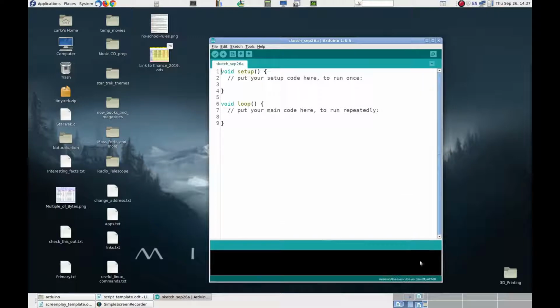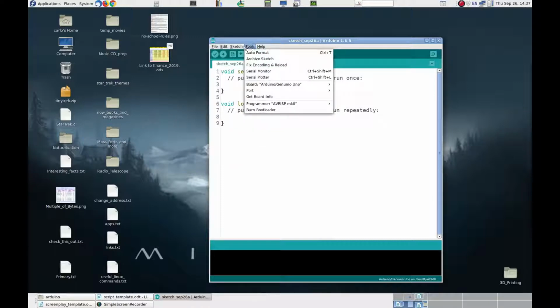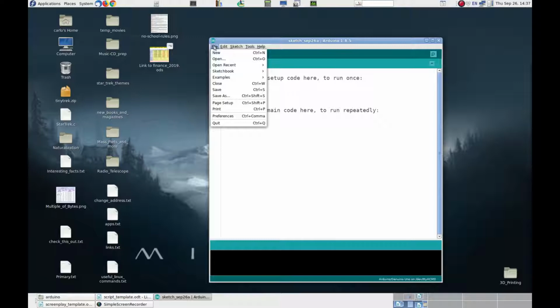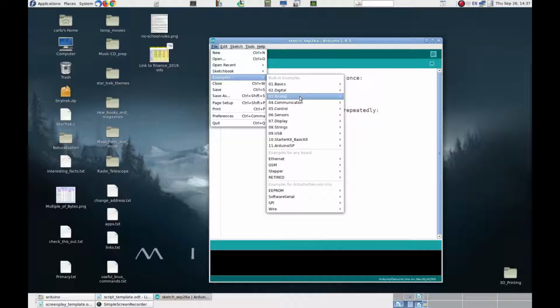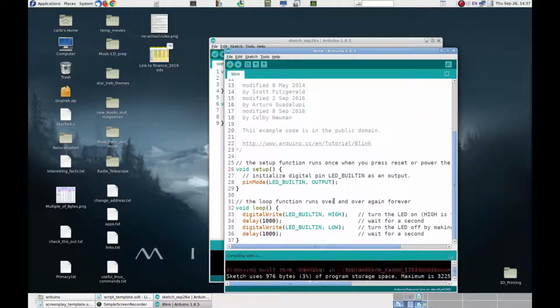Again, also with this version, like for Windows, we have a template already made to start coding right away. But let's see if this works fine. So let's check the menus. They're all here. Perfect. Now let's try to download an example. Basic one, Blink. And here's the code. We can compile it. Clicking over here and verify also, of course, that it is written correctly.